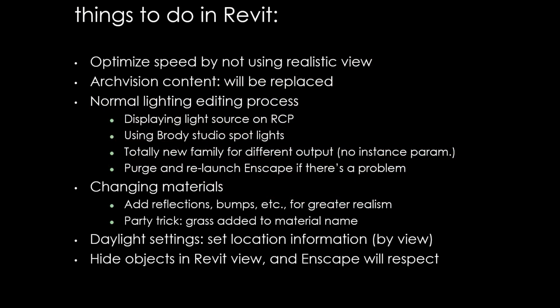You can change the name or append the name of a material in Revit. You can add grass or short grass or tall grass to the material name, and it will actually become essentially carpet. Really shaggy carpet, but it becomes carpet. But if you do have somewhere where you see actual grass or where you have other planting material, sometimes changing that name can really make a big difference.